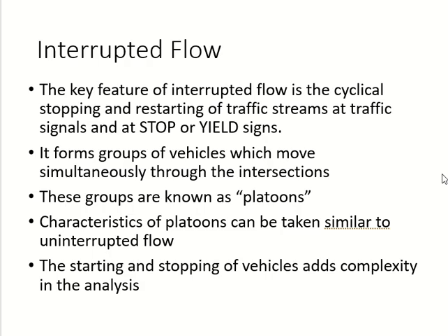Is there any element if the car is crossing or the pedestrian is crossing? So these equations cannot work at intersections, because they are missing the important part of the intersection, which is stopping because of some other reason. Got it? So these equations are mainly for uninterrupted flow facilities, because interrupted facilities are under the influence of other movements.